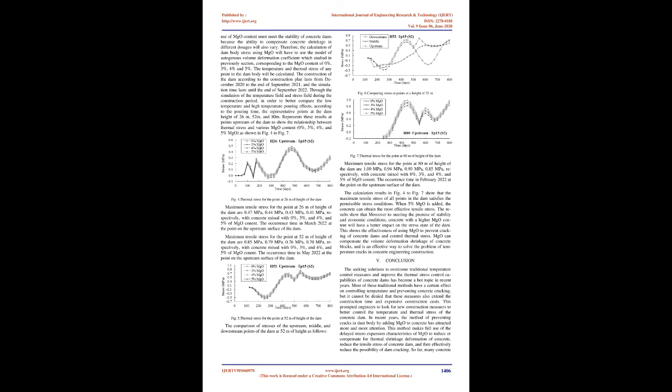For large concrete structures, durability and performance related to temperature state and crack resistance are very important. These are elastic modulus, Poisson coefficient, tensile strength, tensile deformation, viscoelasticity, free volume deformation, autogenous volume deformation, thermal expansion coefficient, thermal conductivity, and water permeability.